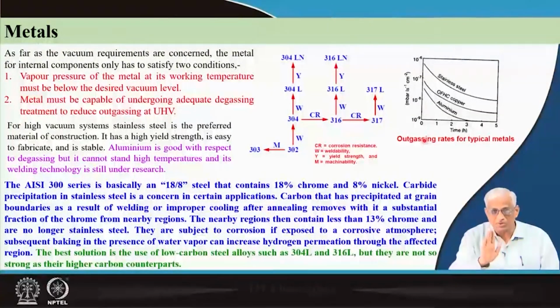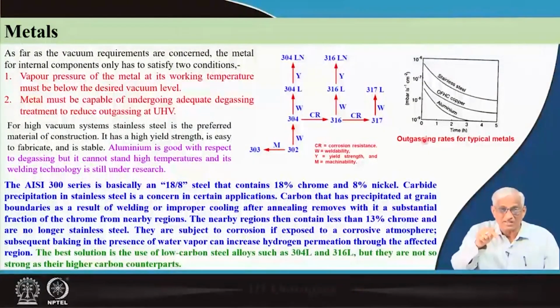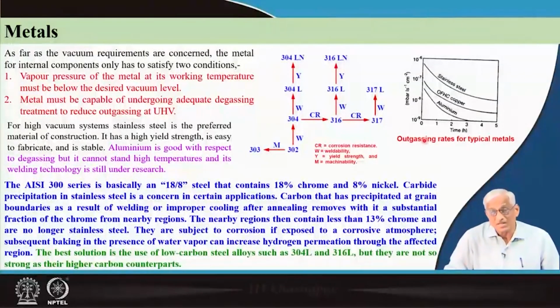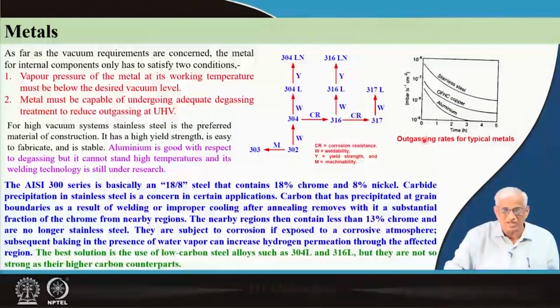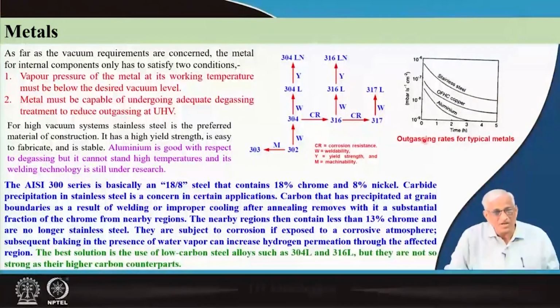That means the up and down, the roughness of the plate, is of the order of the wavelength that is falling on your face and getting reflected. That means it is submicron level, 0.1 micron type of polish. It is entering into 2000 angstroms type of thing. Then only your apparent area will approach the actual area, and if the area is very less, the degassing problem is less, because for a specific unit area there is a degassing which is a property of the material. If the area is much more, then you are in trouble. So, it is only the top surface that matters.